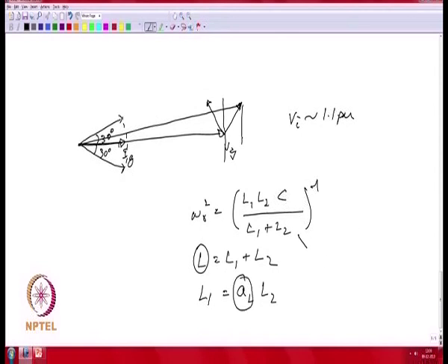You would then get an expression of the form L is equal to (1 plus AL) the whole square divided by omega r square into AL C. So you can look at this expression, which is the constraint between the value of L, AL, omega r and C, and look at a few minimizations.